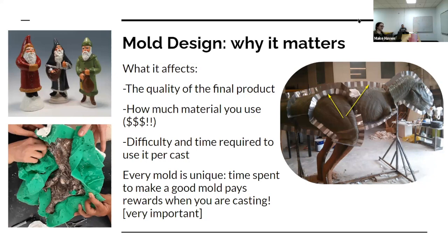The design really affects the time that it takes you to make each individual cast once you start actually using it. And one thing I will harp on quite a bit is that any small thing that you have to do during the course of molding and casting becomes more and more of a black hole of time. If you have to clean something up off of your cast because you didn't take the time to make your mold properly, that will snowball over time, and you'll end up spending an awful lot of time doing that rather than taking the initial moment to do it right the first time.